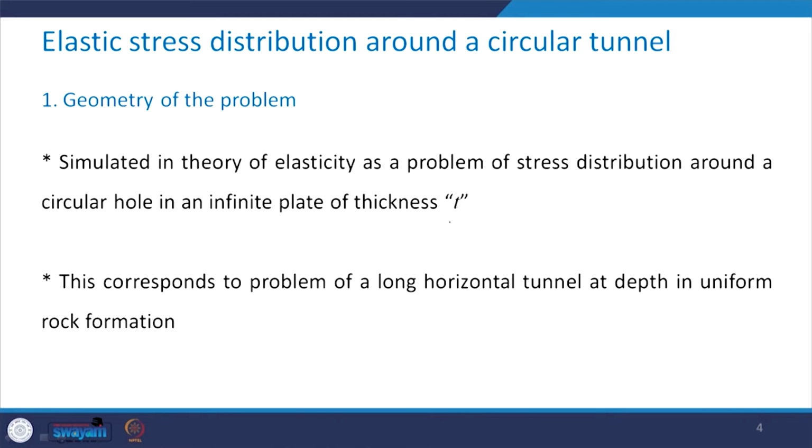This is simulated in the theory of elasticity as a problem of stress distribution around a circular hole in an infinite plate of thickness T. And this problem of a circular hole in an infinite plate of thickness T can correspond to the problem of a long horizontal tunnel at depth in a uniform rock formation.